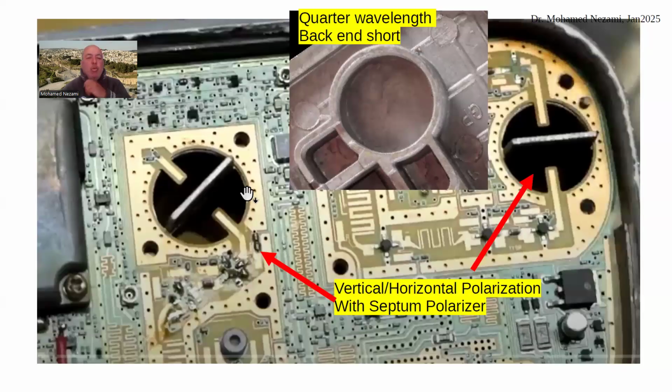So they do this so that this is still balanced, and I don't know why this particular LNB has only 3 channels, where this programming had only 1. Okay, you can see here the VIA is connected to ground. So if somebody thinks the signal comes in and goes through a VIA to the other side of the board, no, it doesn't. This is grounded.